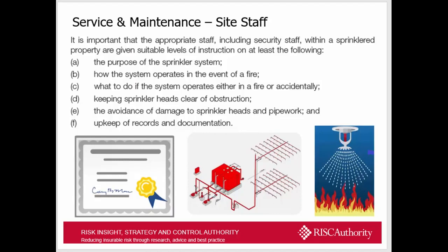So, site service and maintenance. Site staff, as we can see there, it's important that appropriate staff are given suitable levels of instruction on at least the following. They should understand the purpose of the sprinkler system, what it's there to do. Is it a property protection system? Is it a life safety system? Is it a suppression system, or is it a controlling system? How the system operates in the event of a fire. What to do if the system operates either in a fire or accidentally.